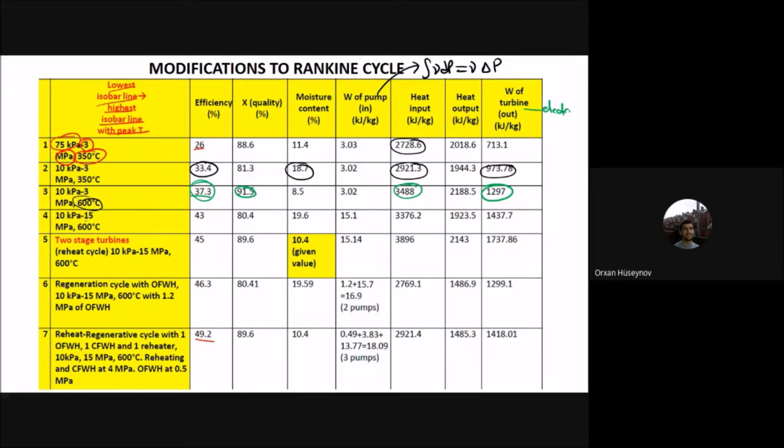Now we are increasing the pressure here. So I can write what happens at each step. In the second step, P condenser drops. Then the peak temperature increases, and now what we are doing is that P boiler, the boiler pressure, increases. So instead of playing with the temperature value here, we are playing with the pressure,